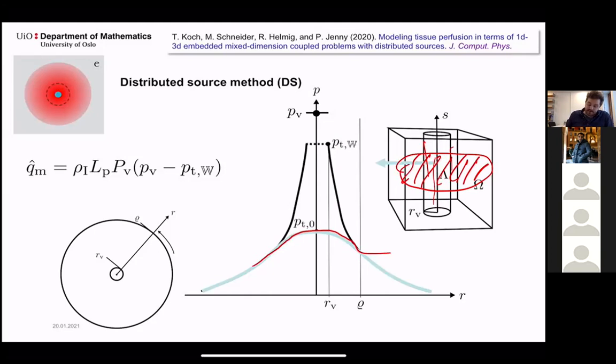And now our problem is nice for numerics. So now we can solve this pressure solution. But the problem is this is actually not the real pressure. So what we need to recover is this pressure up here. It's the pressure on the surface, and we don't have it anymore in the numerics now. But luckily for this linear problem, we can actually use this analytical solution locally to reconstruct this surface pressure from the regularized pressure that we have down here.